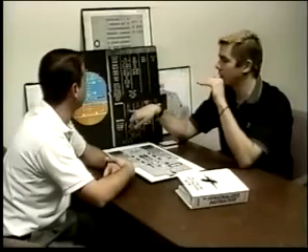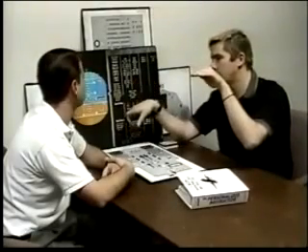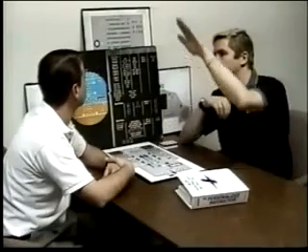I'll also have an armed climb mode there. I will cruise then at 10,000 feet, even though I have 15,000 feet in the window, until I reach the constraint waypoint. Once I'm no longer constrained at altitude, it'll automatically re-engage climb mode and climb up to fly to the 15,000 feet. If it encounters any other constraint in there, the same thing will happen. It'll level at that constraint altitude, the alt constraint will be engaged, climb mode will be armed until it's no longer constrained and can climb up. Once it reaches the FCU altitude window, it then goes into alt.